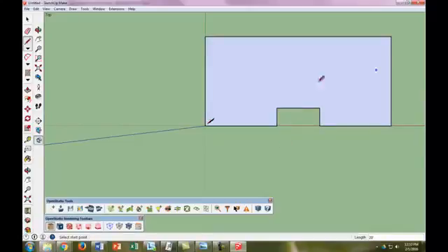As soon as I close a complete shape in SketchUp, it's going to color it for me, which is really nice. Now let's draw the separations for the bathroom and the mechanical room. I know I start at this end point, and I know my bathroom's 9 feet, and I go over. Now, this is the cool thing. You see that SketchUp uses this as a reference point, and you can see that green dotted line there. So that's really nice, because that way I don't need to worry about how far that wall is.